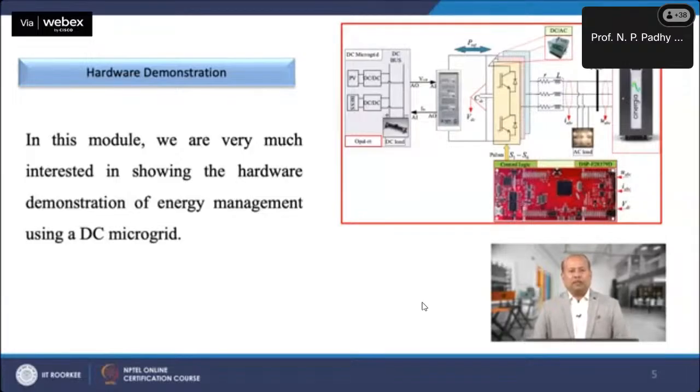This DC bus is connected to the DC input side of the IGBT stack. The AC side of the IGBT stack is connected to the input side of the MCB through an inductor. The output side of the MCB is connected to the grid emulator. The bulb is connected at the MCB point, which acts as a parallel AC load.